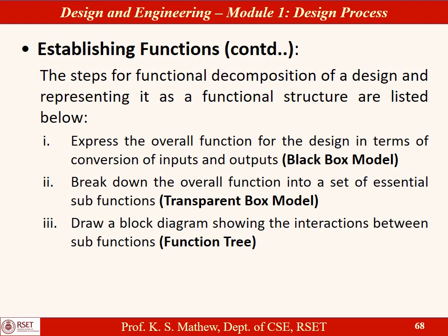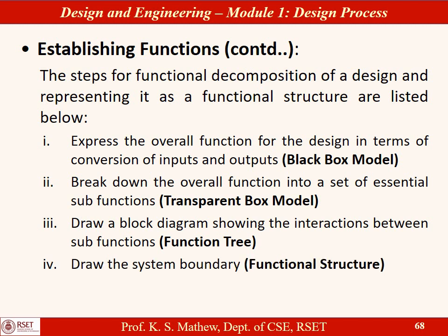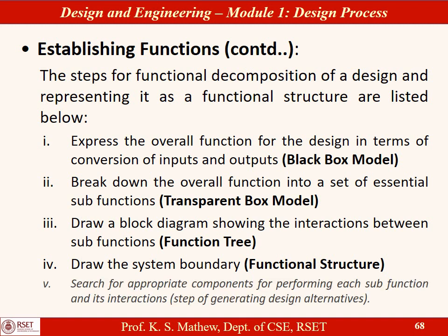Now, draw a block diagram showing the interactions between the subfunctions, that is the function tree. Then draw the system boundary and show the interrelationship between all the subfunctions and the function, which is called the function structure. In the next stage, we will look for appropriate components for performing each subfunction and its interactions. That is the step of generating design.